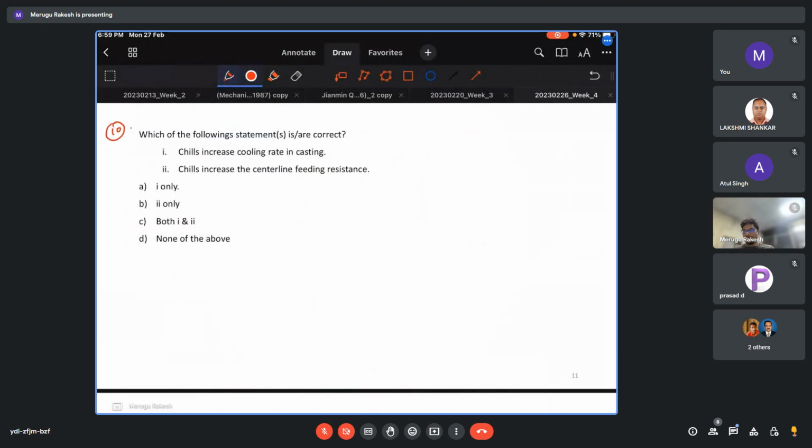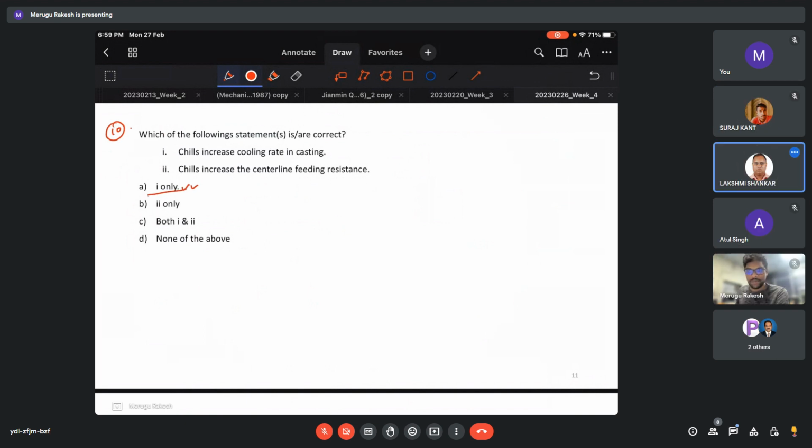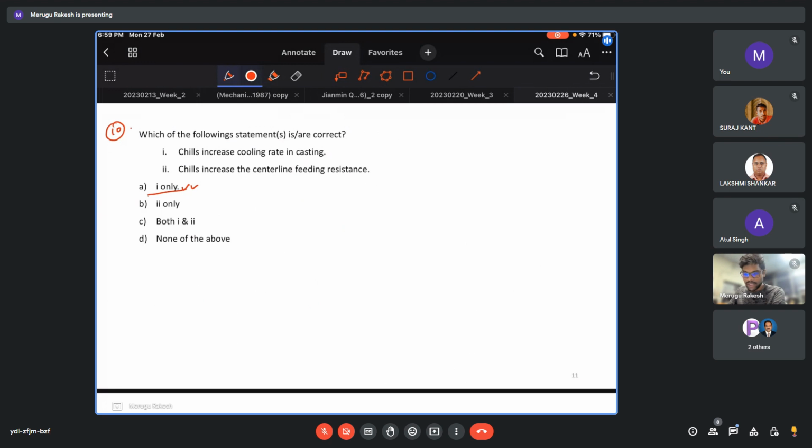Yeah, go ahead. Sir, it is the first one only, that chills increase the cooling rate. Yeah, correct, because chills are used as a heat sink. That is the correct option.